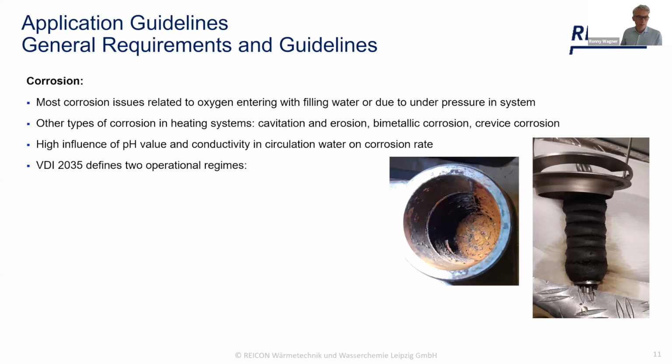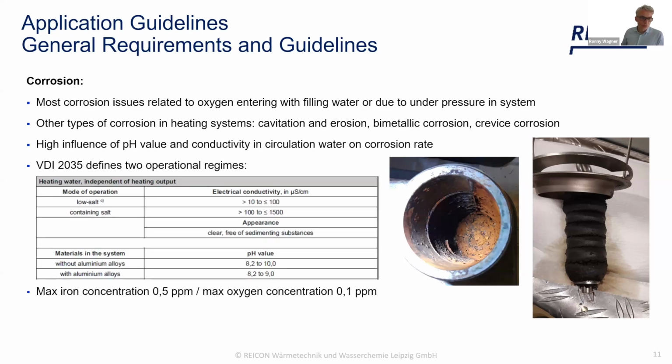In the VDI 2035, there are two different operational regimes, which is a low salt containing system with a conductivity between 10 and 100 microsiemens. This is if you're doing a demineralization for your makeup and filling water, or a salt containing water, which is between 100 and 1,500 microsiemens for softened makeup water.